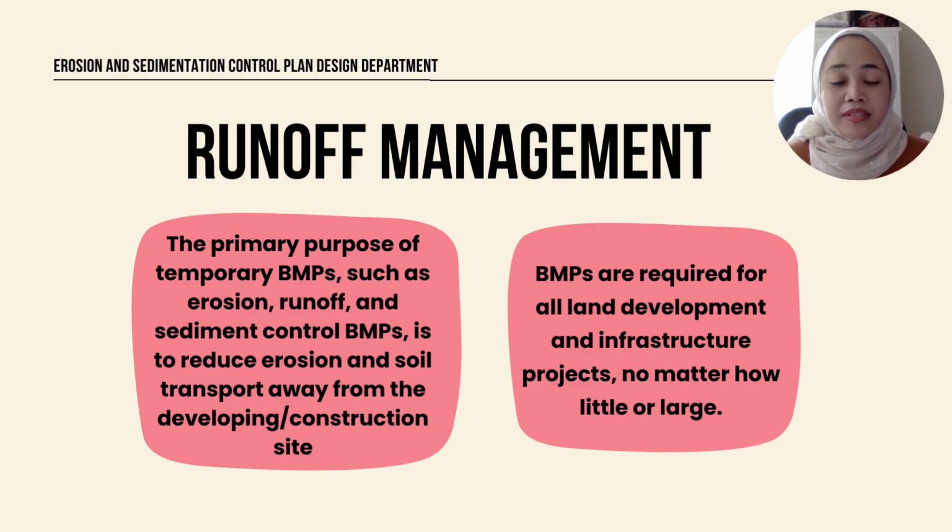Next is runoff management. The primary purpose of temporary BMPs such as erosion, runoff, and sediment control BMPs is to reduce erosion and soil transport away from the development or construction site. BMPs are required for all land development and infrastructure projects no matter how small or large.